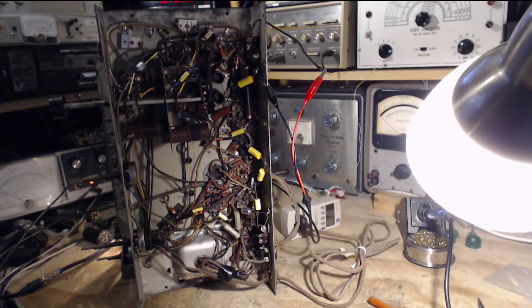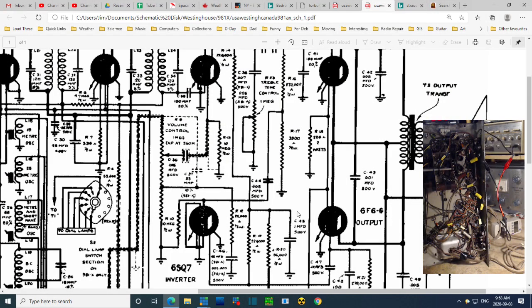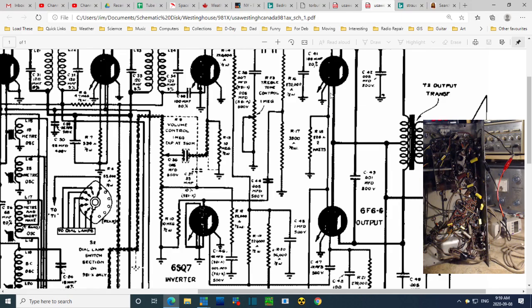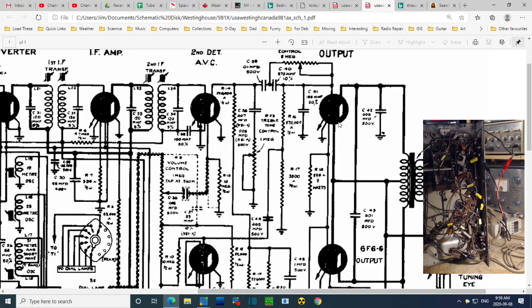Okay, let's take a look at the schematic and see if we can figure out a difference between the two screens. Why? First of all, this is probably the screen here. No. Oops. This must be the screen. Oh, I have to play guessing games here. No, that's the cathode, because there's the cathode resistor. This is showing high voltage. It's heavied up. So we got the two high voltage, plate and screen. So look, the screens are connected solidly by a wire.